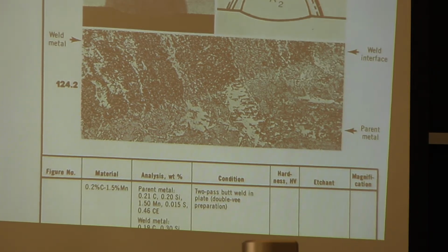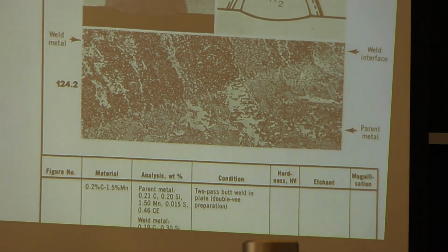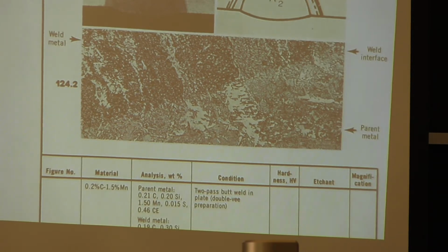If you look at that weld metal, it's just full of little bitty spherical oxide inclusions. And you might say that's bad, except it turns out it's good, because it causes nucleation when you have this transformation, as it's cooling down from FCC to BCC. Those little oxide inclusions will nucleate what we call acicular ferrite.